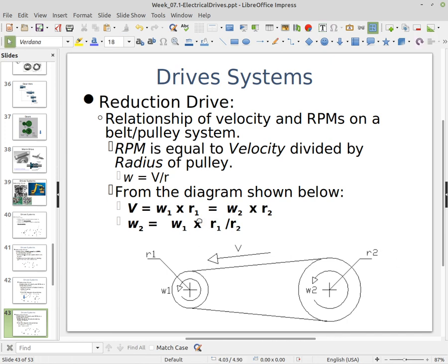All right, so this is showing the angular velocity here, w or omega. And if you wanted to calculate the torque, then the ratio between the radius R1 and R2 gets flipped over. So here our speed is slowing down, right? Our speed at w2 is slower than the speed of the first one because the radius 1 is smaller than the radius 2.